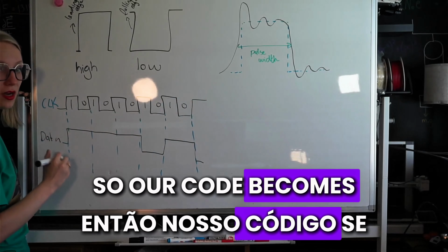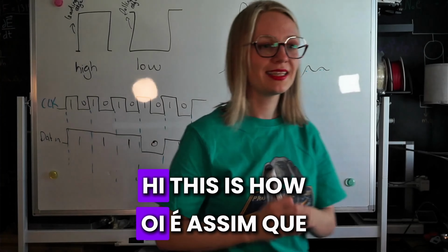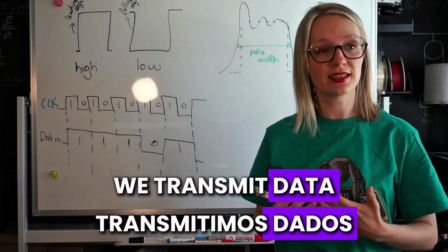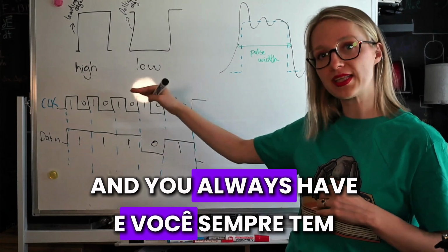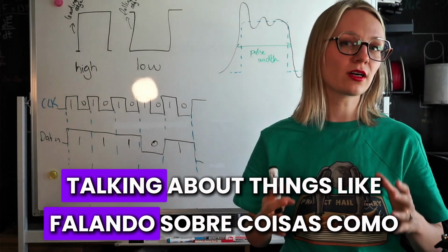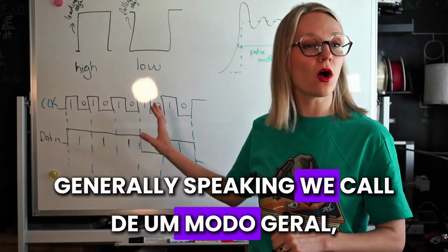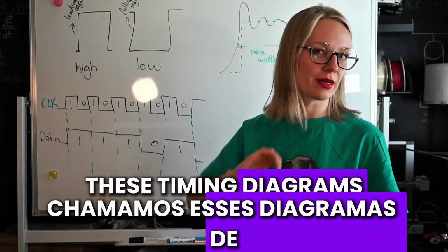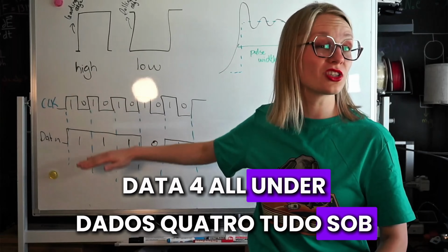So our code becomes high, high, high, high. This is how we transmit data or information using a waveform. And you always have to have it synced up to a clock. Later, you will be talking about things like asynchronous and synchronous clocks. Generally speaking, we call these timing diagrams. You can have many. You can have data 1, data 2, data 3, data 4, all under the same clock.